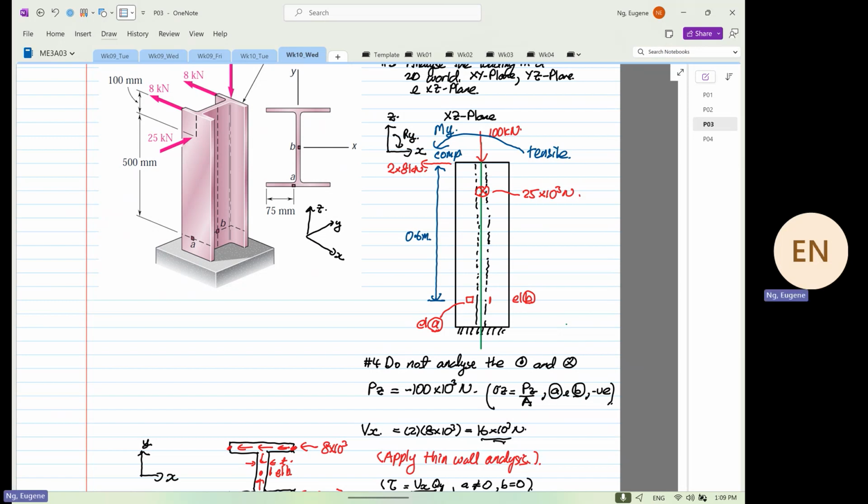You don't need to say, oh, I can't visualize, I forget the formula. Now the axis changes. The normal stress that we calculated used to be stress X, now it's stress Z. What must I do? If you cannot recall how the stress formulation changes the equation, we are taking it from the moment vector. With this, do you need to rely on the formula? What can you see? The head of the moment vector is compression, the tail end is what?